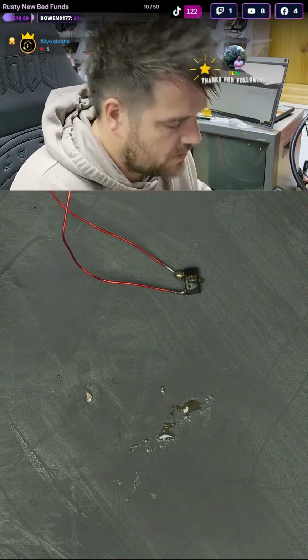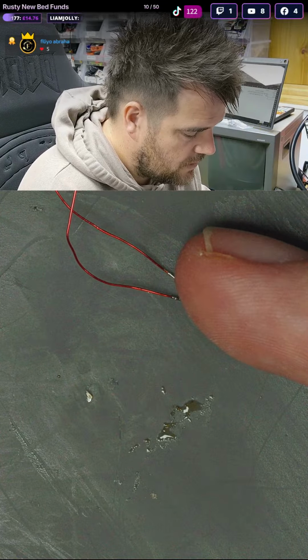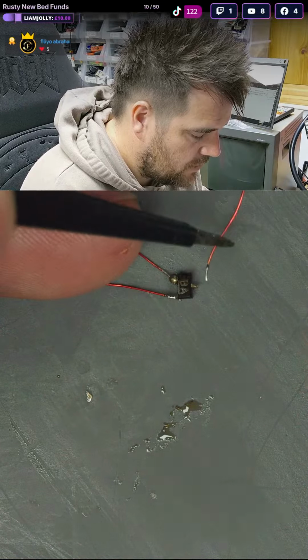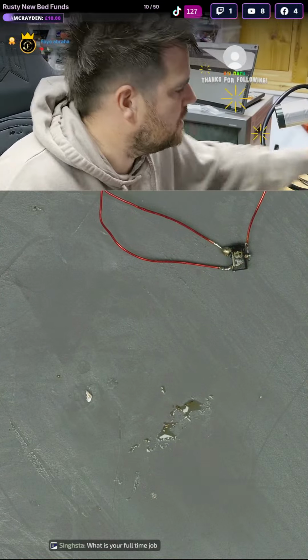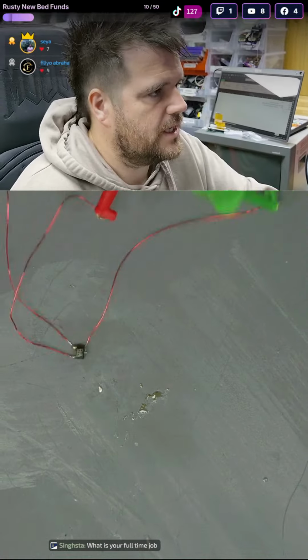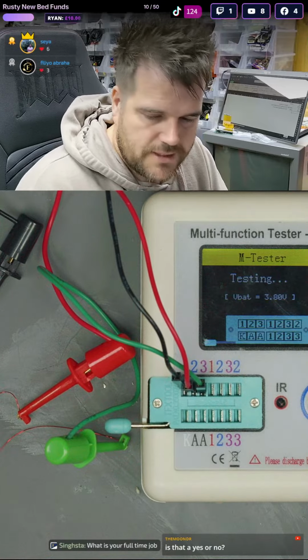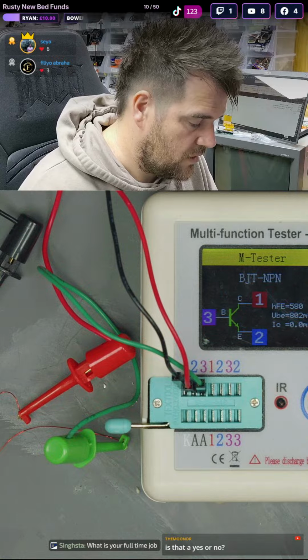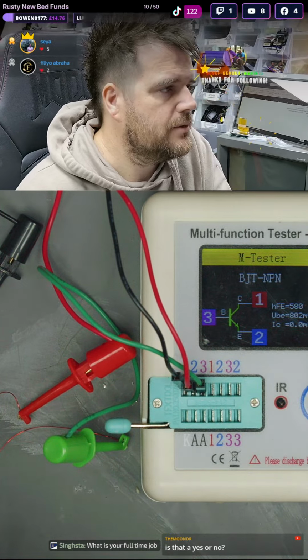Right, it's this last one now. It can't fly off now because we've got 2 wires on it, so I'll just fumble around with my fingers holding everything in place and tack that wire on. So there we go, that's the 3 wires attached again to this little chip. Same again, I don't think this is a diode, I think this is an NPN transistor, labelled wrong. Yeah, look at that.